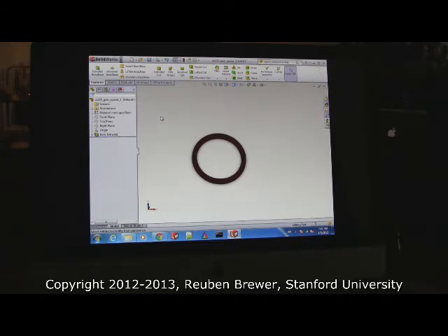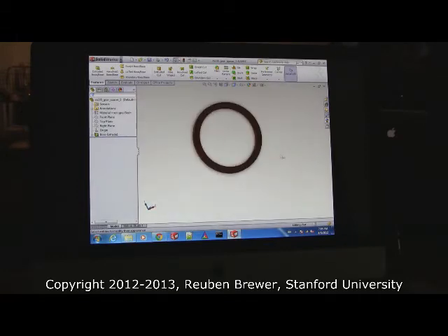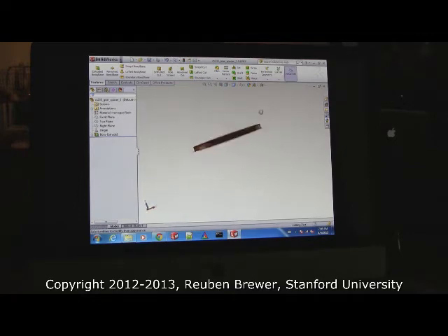So now we've got an interesting object. It's three-dimensional, so it makes sense to look at it from different views. That's why I need a 3-button mouse. Everybody, hold down your left mouse key. Let's do the rotation for now. Hold down your left key, and it doesn't do anything to the object, right? However, we can select things with it. If you want to select a whole bunch of stuff in an assembly, that's how you do that. We don't want to do that. Okay, the way I rotate is I hold down my scroll button. Not scroll, I just press that as a button, and then I move the mouse, and that rotates it. Can everyone rotate their object like this?